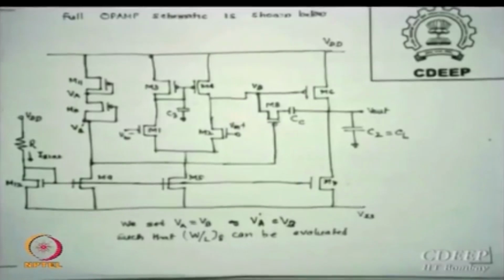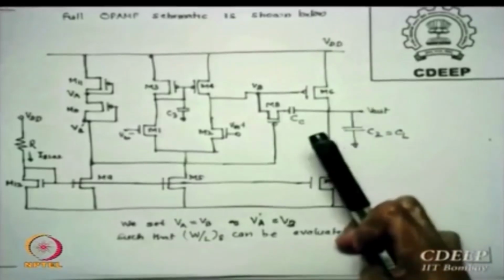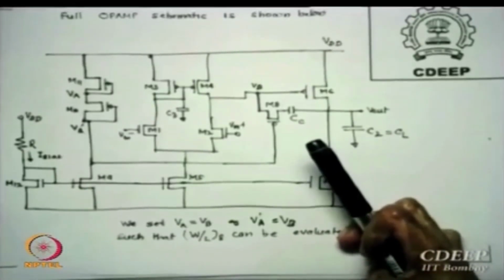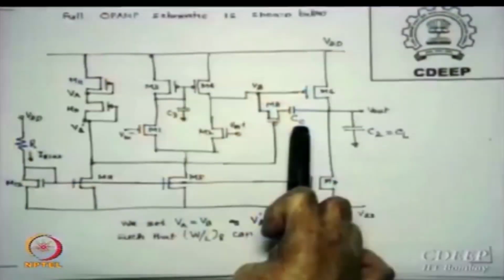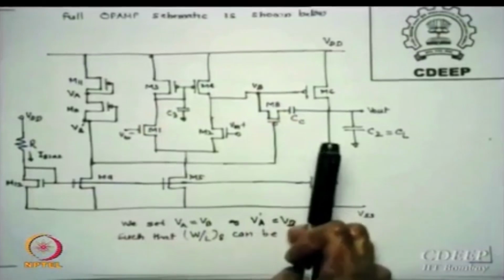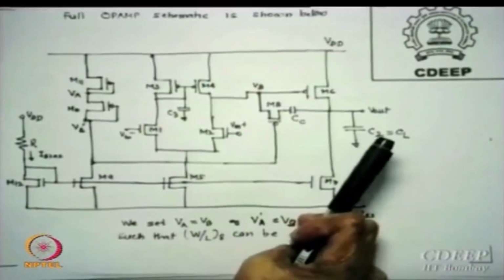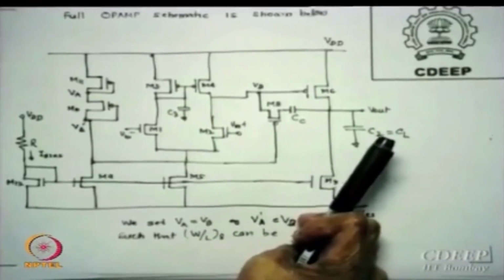Okay. Sir, for CC also we need to put one MOS capacitor. CC is a variable. CC is not given to me. Is that clear to you? CC I will make a choice from the phase margin I choose. So in the circuit I need to put a MOS capacitor. This CC is connected here, right? On the actual chip it cannot be left as a parasitic; that will not be equal to CGD's values. It is much higher, not 2 pF, it is in femtofarads for parasitics, whereas this is in pF, you got it? So that value physically you will have to put.